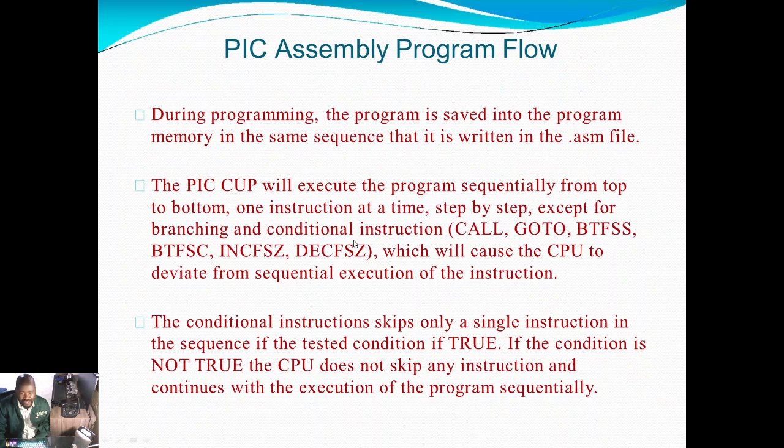When you write your assembly language program and program your microcontroller, whatever you have written in your assembly language is going to be saved in the PIC's program memory in the same sequence as your assembly instructions. Meaning whatever you have written is going to be copied and saved in the PIC program memory. Right, but obviously it will be in machine language, not in assembly language anymore.